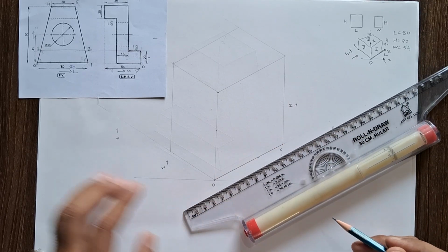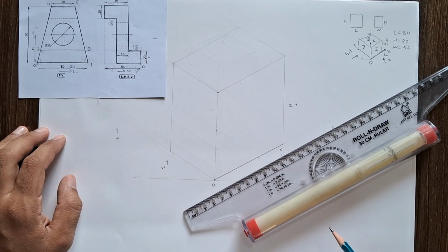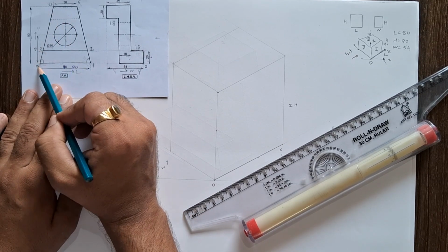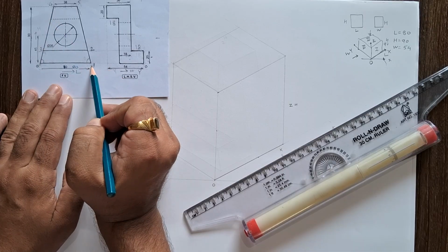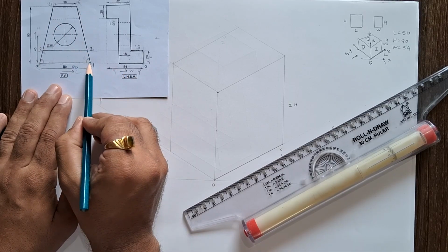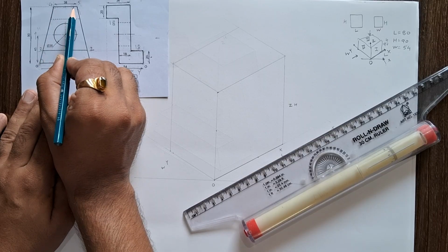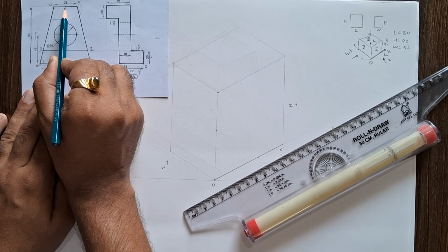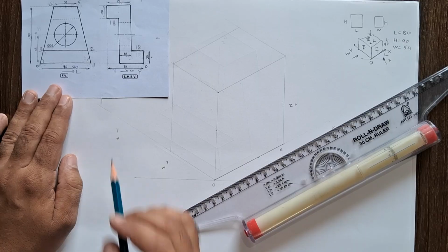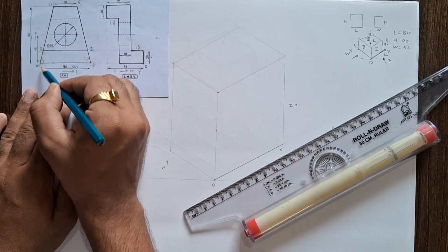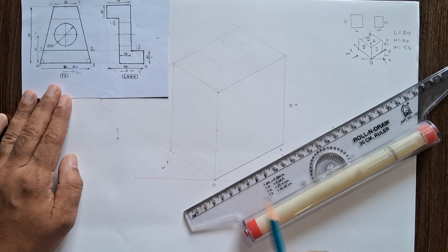O1 distance is 80 mm. Now the angle of this O34 125 edge is not given, but the top edge distance is given. It is 38 mm and it is at the center of that part, center of that object. By marking the 38 mm distance, we can find this slant edge.